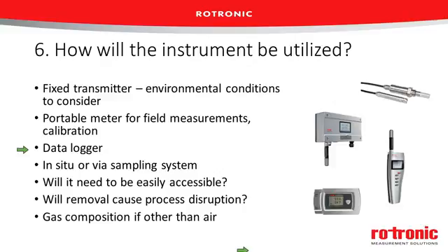Will you be measuring in situ, for example, in a compressed air line or in some other type of pressure device or some other type of enclosed room? Or will you be needing to draw off your air or gas from a certain application via a sampling system? These are all different ways the instrument could be utilized, and understanding if the instrument you choose will have that capability is very critical. Again, you don't want to purchase the wrong instrument at first because it just causes problems.